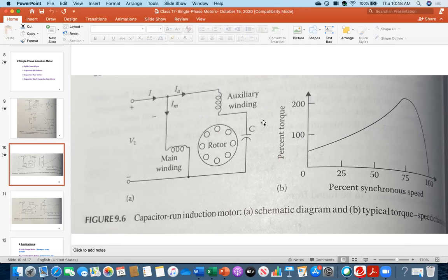Your ceiling fan is not running because it got disconnected. If this is broken or damaged, it means the auxiliary winding path is not working. At the beginning of the class today, we learned that a single phase induction motor is not self-starting. Only one coil is not enough. Ultimately, there is no torque and your ceiling fan stopped. So in most cases, the issue is with this path.